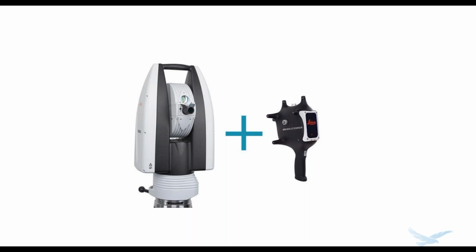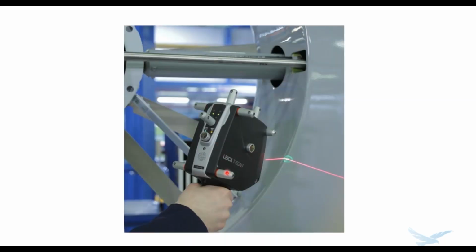And these can work together with handheld systems. So for instance, you can use this handheld scanner. It's got these little nubs on it, which have these little tracker dots. And the tracker is constantly following these and just tracking its position. And so you have the benefits of the handheld, where you're able to get up close and reach your arm into things. But it's constantly being mapped onto the larger coordinate system provided by the laser tracker, so you have much better accuracy over distance.